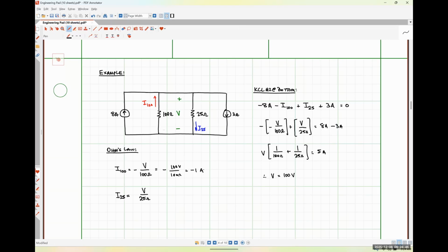By all means, tell me what part of my algebra you weren't catching. You weren't the only one with a confused look, by the way. So I100 is negative, and then flowed into the negative terminal first. I100 is negative because we arbitrarily chose the wrong direction. So in reality, negative 1 amp up is the same as 1 amp down.